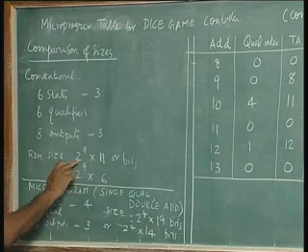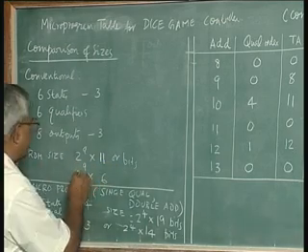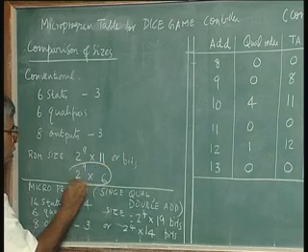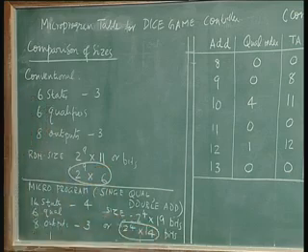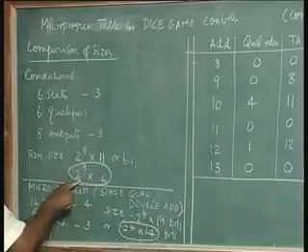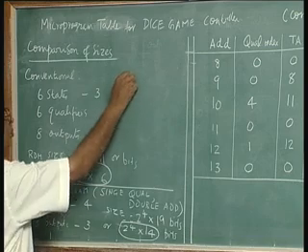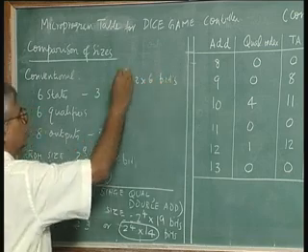So, in this case it is 2 power 9, 2 power 9 is what? 512. So, let us go with the coded output case. So, in the case of conventional ROM, it is 512 by 6 bits, conventional.